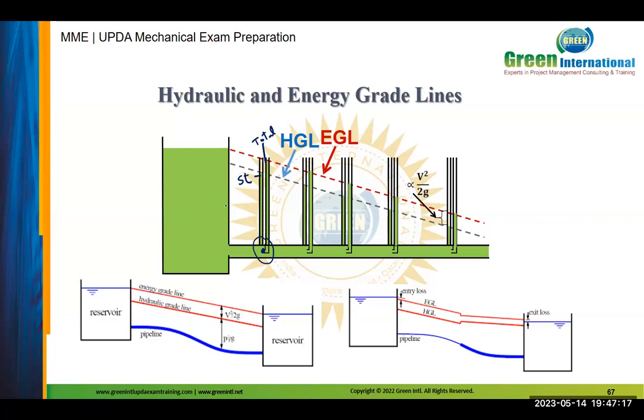And all the time we talk about this point. What is the difference here? Total minus static, as per the equation: H static plus H dynamic equals H total. So static plus dynamic equals total. The difference between total and static is equal to dynamic, which is V square over 2g, the kinetic energy part.